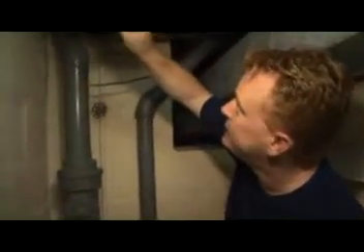It's going to take your warm, heated air with it. And then we have a penetration in the ceiling where the ductwork is. It's not sealed, so you have an opening in the floor. And these are all spots that we're going to want to do something about. Sealing that up with foam so air can't get up, and sealing the penetrations with the pipes, sealing that up with some foam so air can't get in there. And then closing off the ventilation in the crawl space.